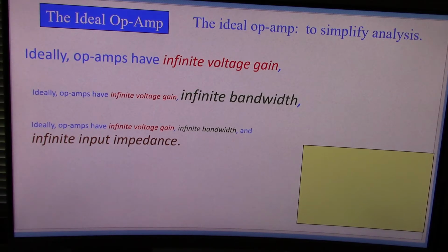if you don't have a high input impedance, then what happens is the devices that are supplying the power to it are also powering this operational amplifier. And you don't want to do that, because what that does is load down the devices upstream. You don't want to load up the devices upstream. You want to have the power internal to the operational amplifier to take the intelligence of the information coming and amplify it.